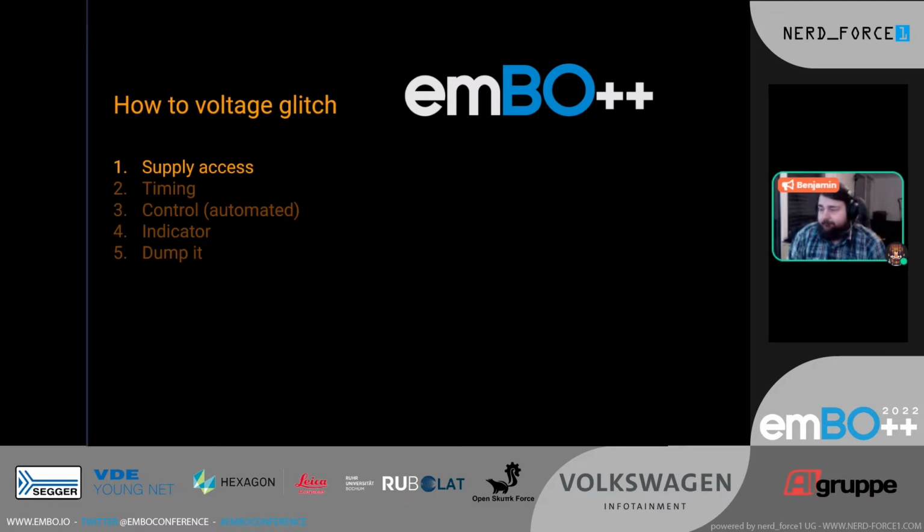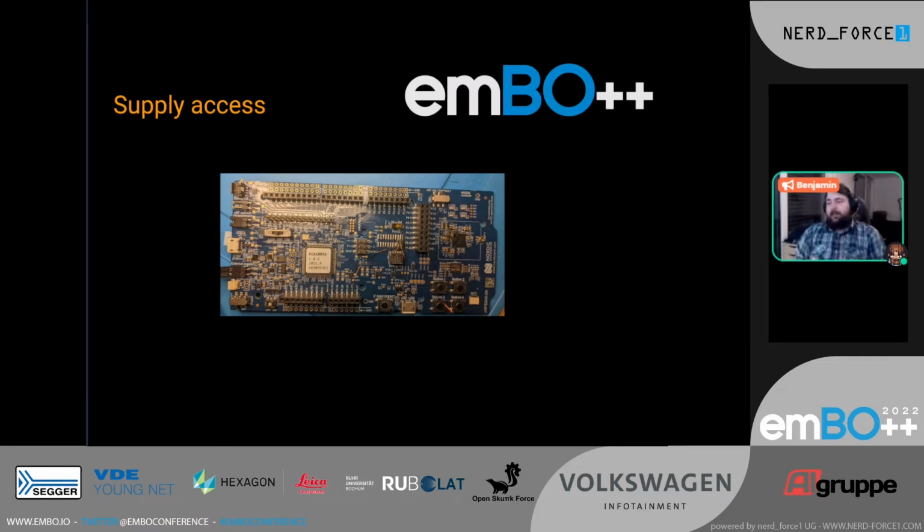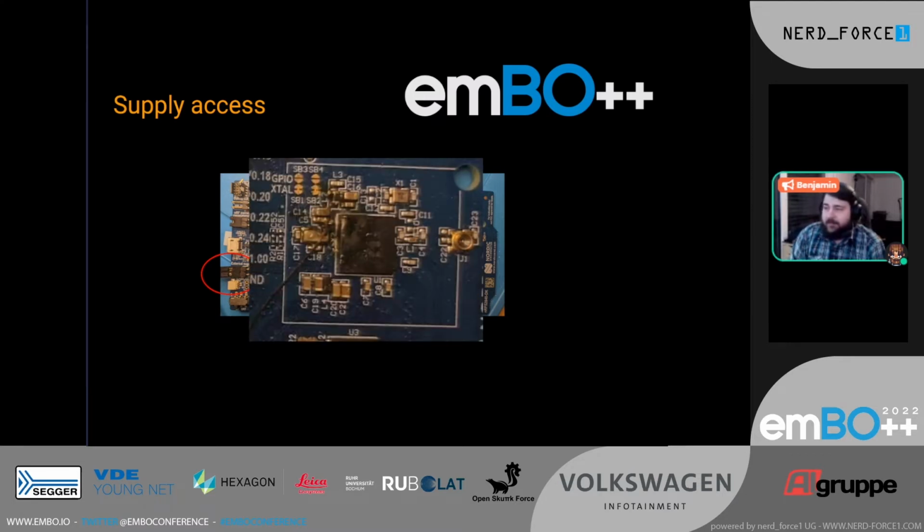Well, this is a dev board, and it has a nice header labeled external supply there, but if we attack there, there's a whole lot of dev board in the way until we get to the actual chip. And these components all have some decoupling capacitors that we need to discharge to drop it. They have some capacitance internally we need to discharge. There are just so many variables in there. It's going to be hard. It's going to introduce extra noise. So instead, let's focus on our actual target.